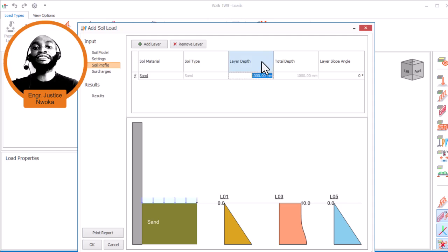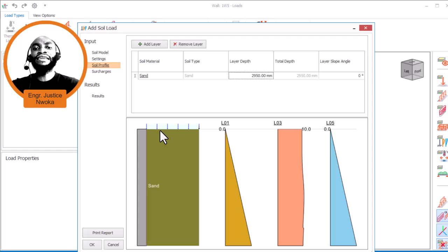But if you feel that the sand will not cover the basement evenly, then you can put the height of the sand, okay? For example, we have a partial basement, okay? Basement that part of it is inside the ground, and part of it is above the ground. So that's a partial basement. But if you have a fully submerged basement, then you have to put the total height of the basement here and then press enter, okay? You can now see that this is a fully submerged basement.